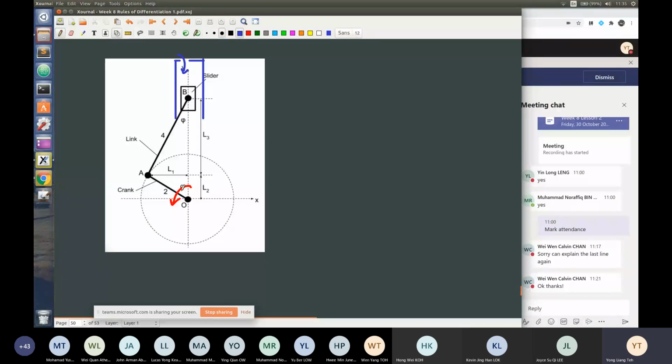Then subsequently, when this piston is after the angle of pi already, it's going to rotate back. So then this slider is going to compress. You can imagine, when your crank is at this position, this is going to have maximum volume in this cylinder. Then after that, your crank starts to go back, and this slider starts to push back. When this piston pushes back, it compresses.